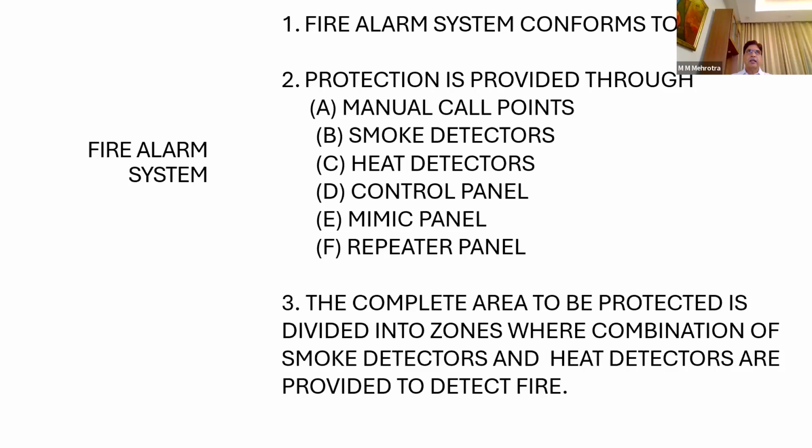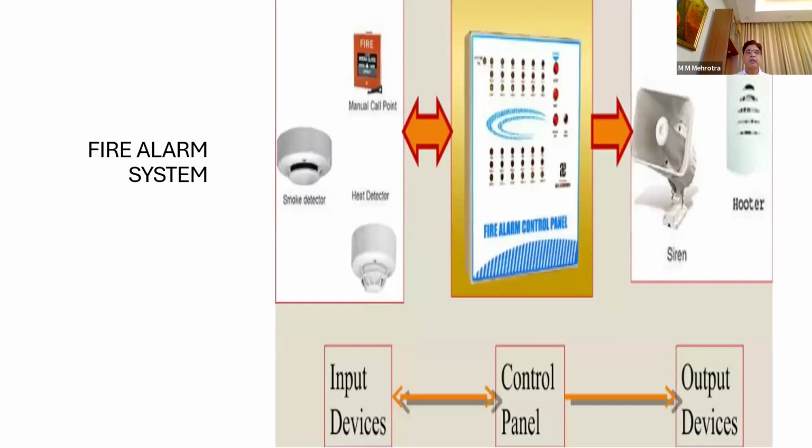I am equating it with electrical wiring. In case of electrical wiring, there are fans, lights, small power points, some 8 power points. They are being connected to a distribution board. Here, they are the components which are there on ground. They draw very small current. This is supplied through a battery bank. Normally it is 24-volt DC.